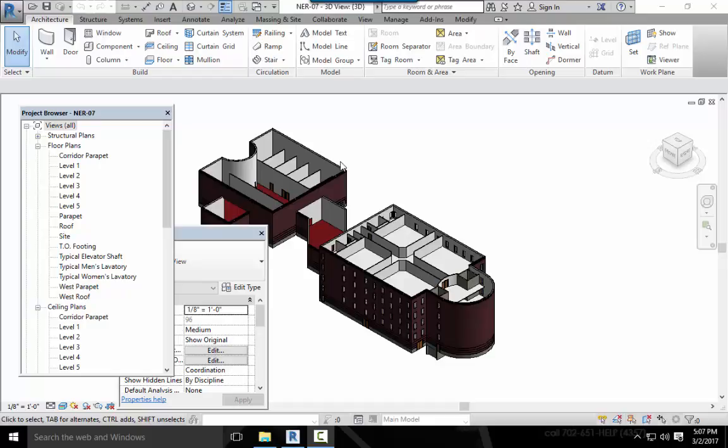All right, chapter 7, roofs. Roofs come in all shapes and sizes. Given the nature of roofs, there is a lot to think about when you place a roof onto your building. If it's a flat roof, pitch is definitely a consideration. We do all realize that there should never truly be a flat roof. Even a flat roof has slope to it. So as designers and architects, you still have to think about, how do I get water off this surface?